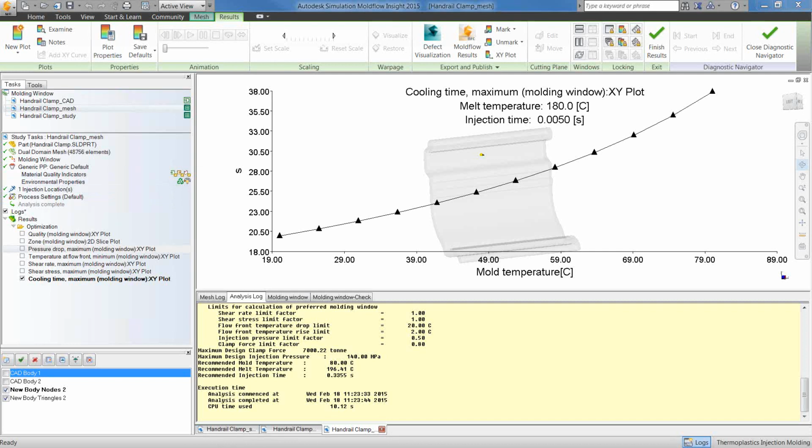So typically we don't recommend creating the entire feed system until you get further into running the next step in the analysis. Yeah, that's absolutely correct. And again, the general assumptions that this solver uses don't accurately take into account feed systems anyway, so I just wouldn't recommend doing that.